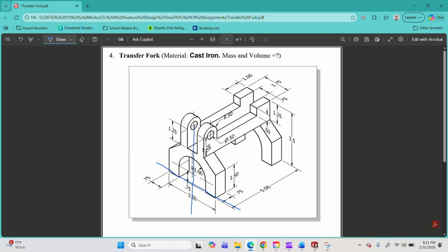And plus, when I go to make other portions of it or cut portions of it, like when I go to make this part right here, I can mirror it across this right plane onto the other side. Why? Because I would have created the plane in the middle. Now, if that plane is sitting off to the side, it's not going to put it where I want it, right? So that is how I'm going to go about doing it. I'm going to make sure my top plane is here, my right plane is here, and I'm sketching on the front plane. Okay. So how am I going to do that?